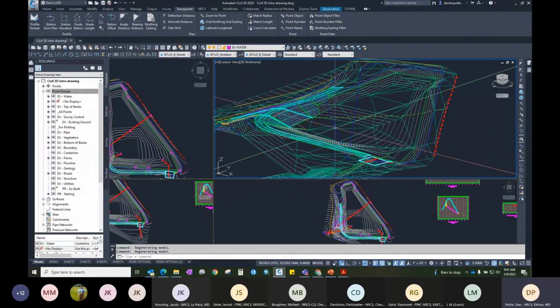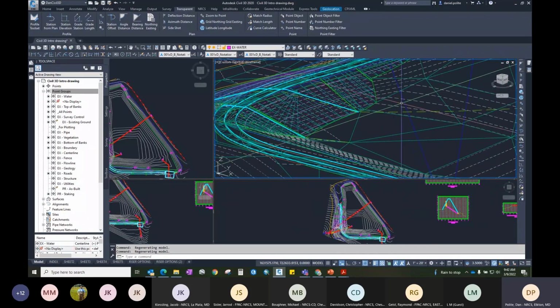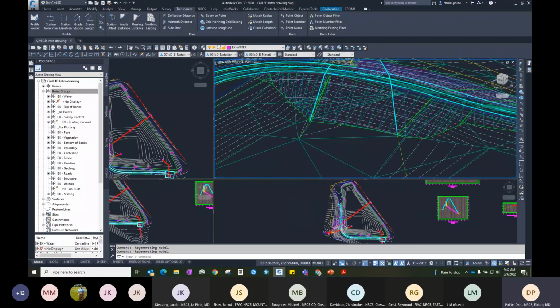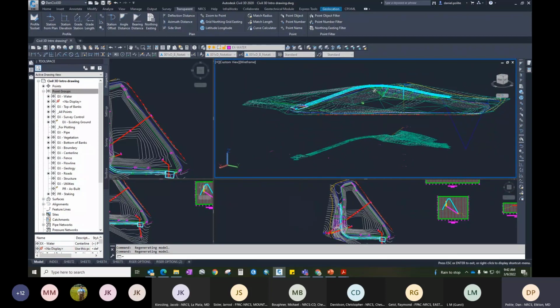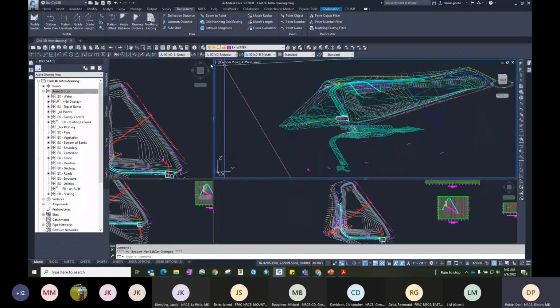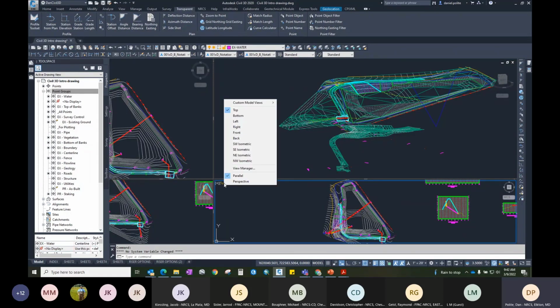So we're looking at that in 3D, and we'll go over the mouse button and how we move this stuff around, but you can zoom in, zoom out, and see what it looks like compared to that surface. So after you get that done, this one is showing top. So if you hit top, again, you can do bottom, left, right.